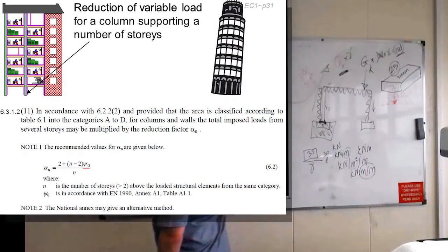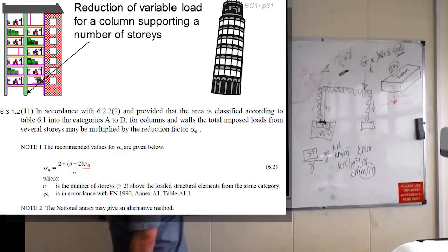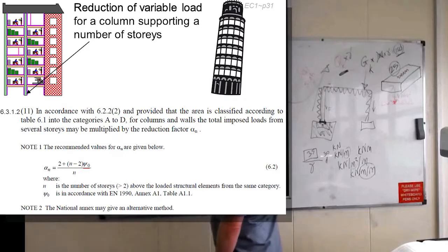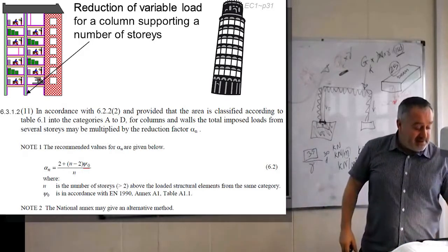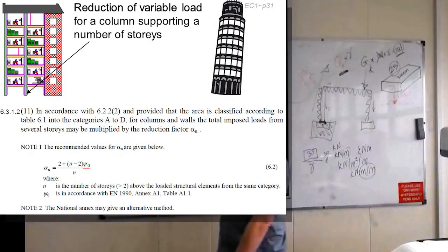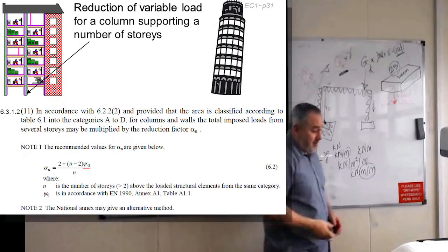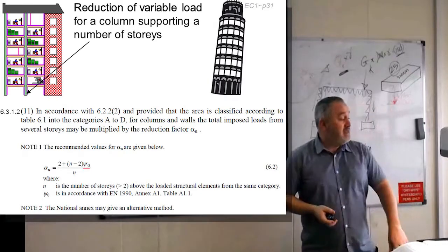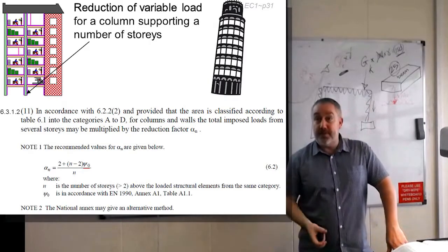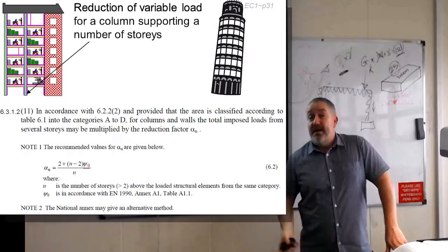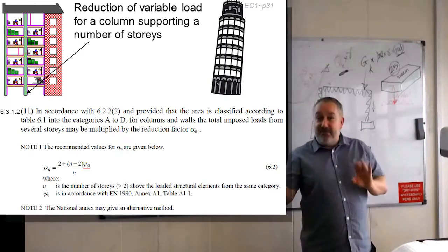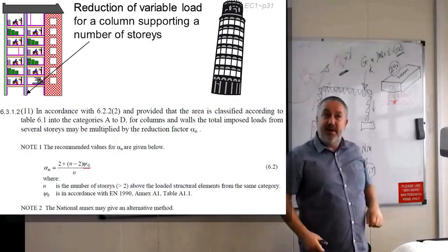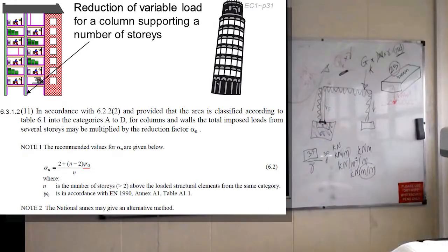So in Eurocode 1, 6.3.1.2.1, equation 6.2, so underneath your table 6.12, you should have this formula here. Now what that is, an example of a variation, is what's the chances that, let's say there's an explosion outside, everybody in this building would run to this side to look out the window.